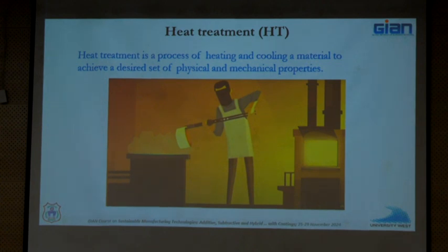Any questions about hipping? Because when you do thermal post treatment, hipping is the first step, right? Where you are essentially getting rid of defects and pores, and to some extent ensuring that your delta phase, etc., is gone. But even if that didn't happen, that is the purpose of carrying out the heat treatment later. So the main motivation for hipping is defect closure, right? Nothing more. So any questions about that, or can we talk about heat treatment then? So let's talk about heat treatment.